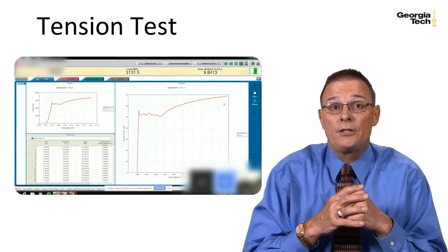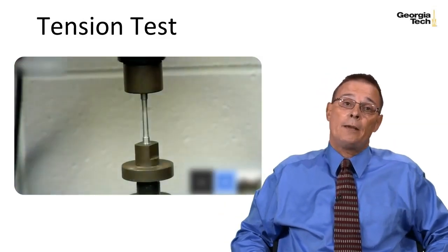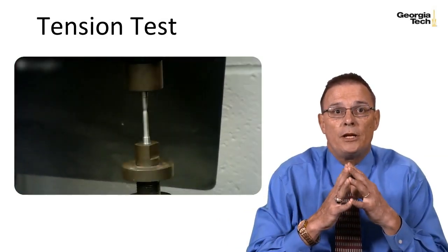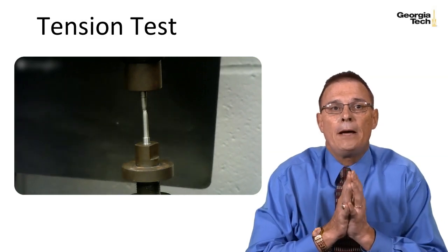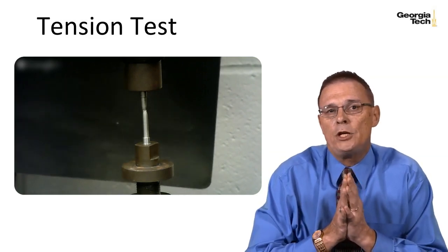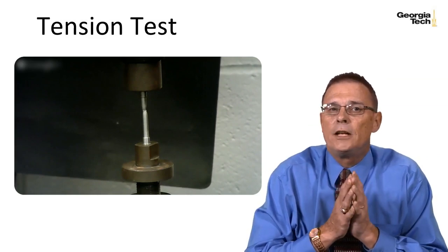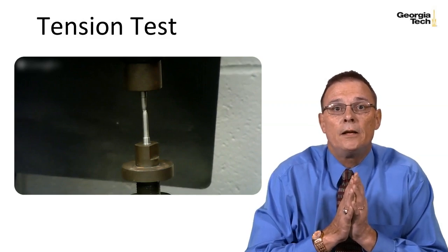As the specimen is continually loaded, you'll notice that it starts to neck down, or become smaller in diameter, until it finally fractures. The specimen used in this test is 1/4 inch diameter steel. It's classified as 1018 hot rolled steel. This type of metal is typically used for things like machine parts or shafts, like the drive shaft in cars. And steel is a ductile material, and we'll talk more about ductility in a minute.